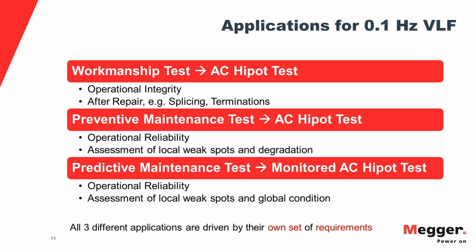The main tool, however, is preventive maintenance. So the periodic testing of the circuits to weed out the critical defects. And we're talking about local weak spots, nothing global. And then as a variation, you can also do some predictive maintenance with the VLF test if you conduct it as a so-called monitored withstand test.